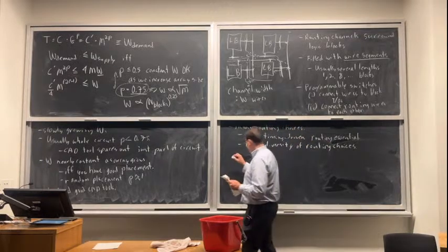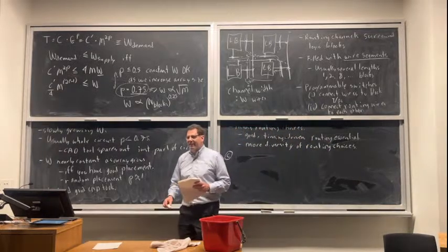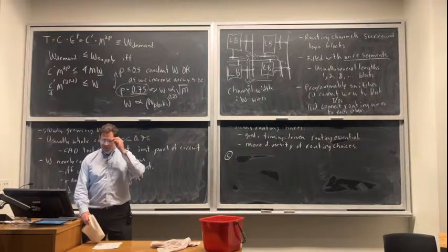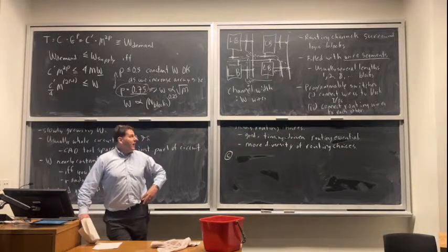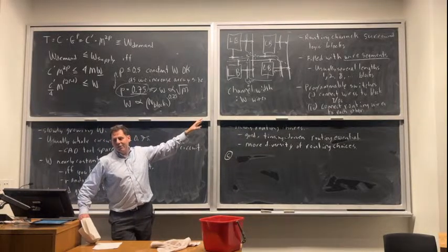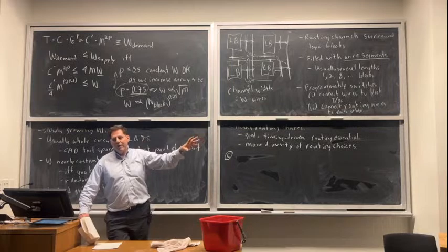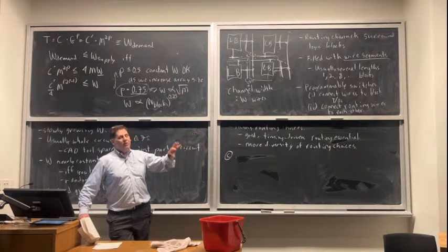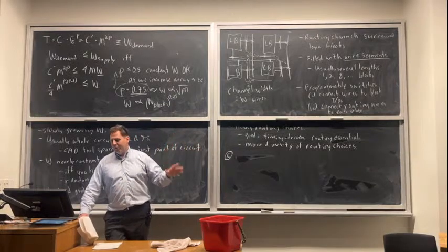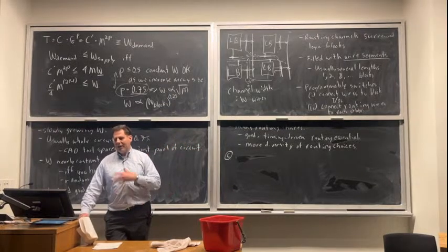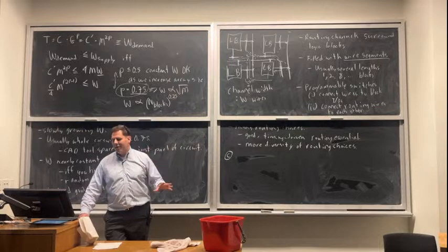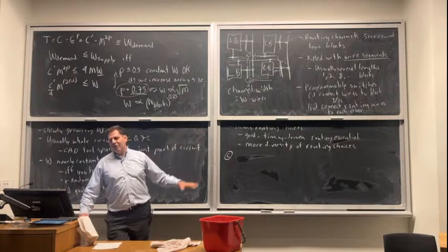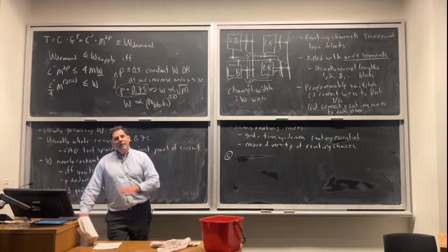I have one question. Sure. At the time that you use this routing architecture to build it up, what did Xilinx have? So Xilinx always liked island style. Xilinx and Altera went in opposite paths. Xilinx's island-style architecture started out simpler. They gradually added more complexity to them. So it wasn't like they were always the same architecture because they used that style, but what went in the logic block, how the routing worked, changed.